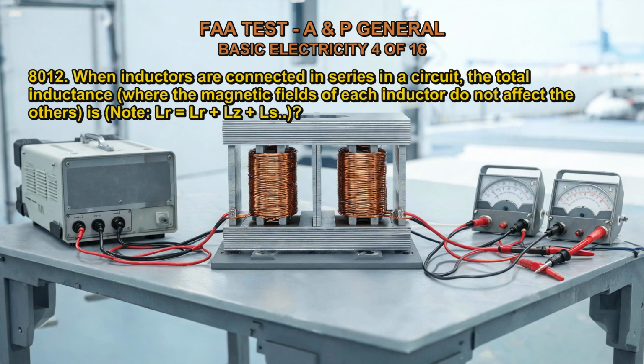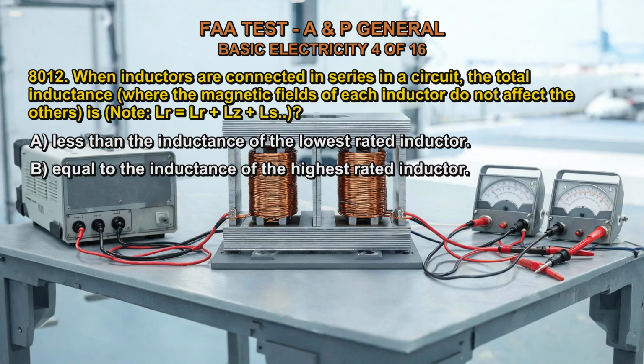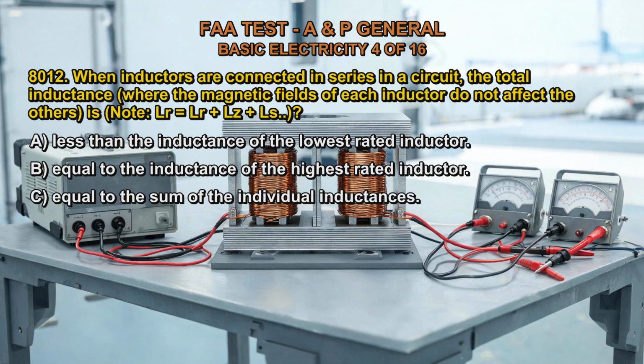Q8012. When inductors are connected in series in a circuit, the total inductance, where the magnetic fields of each inductor do not affect the others, is, note, LT equals L1 plus L2 plus L3. A. Less than the inductance of the lowest rated inductor. B. Equal to the inductance of the highest rated inductor. C. Equal to the sum of the individual inductances.